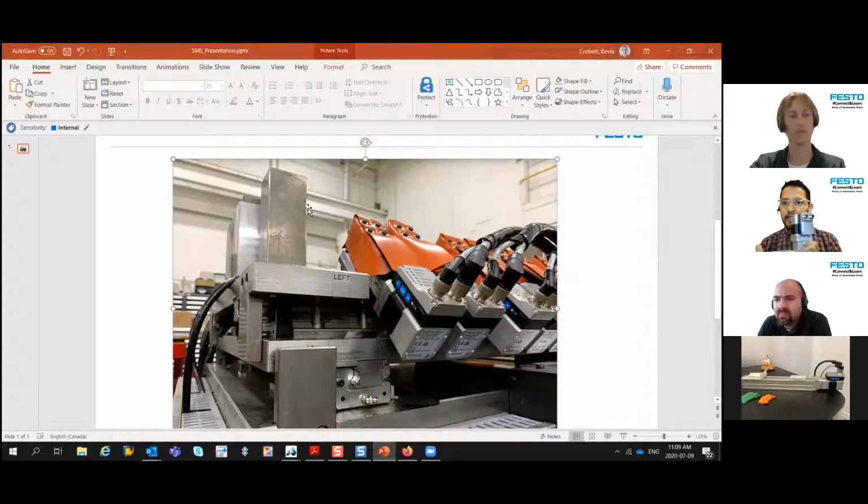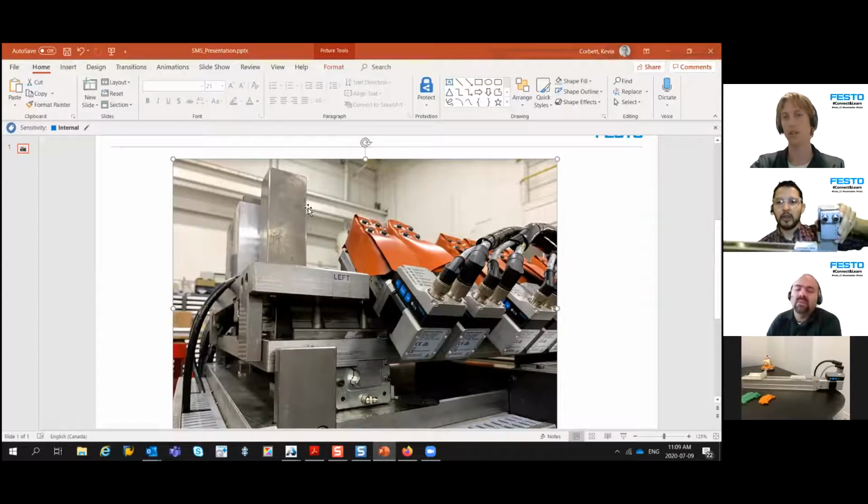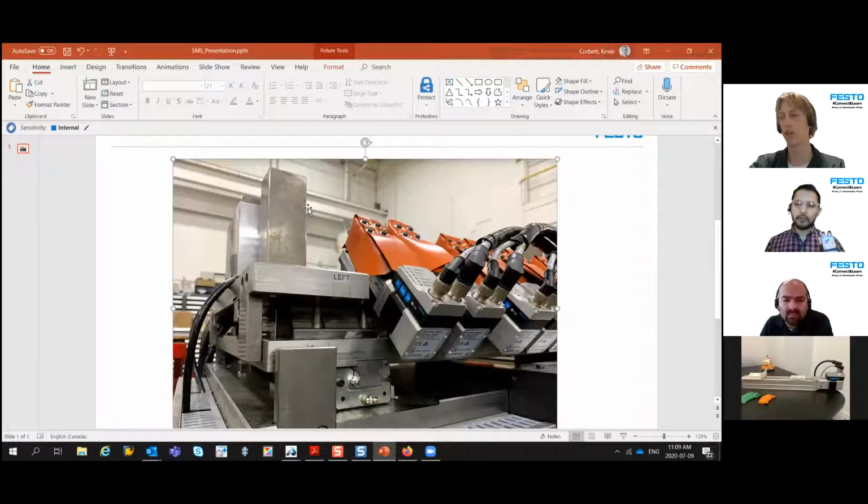And you're controlling this in your case how? IO-Link. But you can also control it via digital IO, right? Yeah, exactly. You could just hook two PLC outputs up to the two digital inputs, and that's all you need, and then you're ready to go.